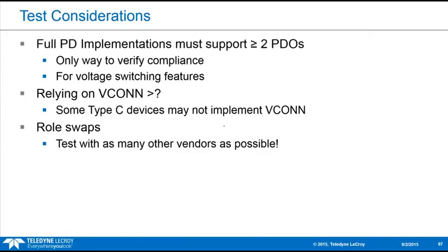Okay, so the USB-IF is finalizing the compliance spec for PD. We are active with that group and are actually working on supporting the full PD compliance plan. They found some vendors actually have configured their devices when they come to these workshops with only a single PDO, like 1.5 amps at 5 volts.